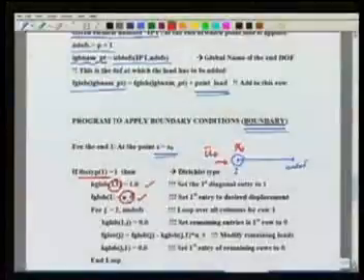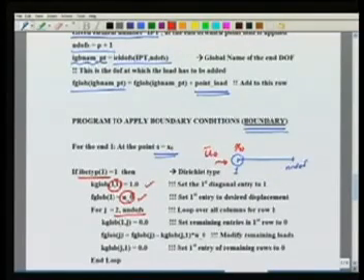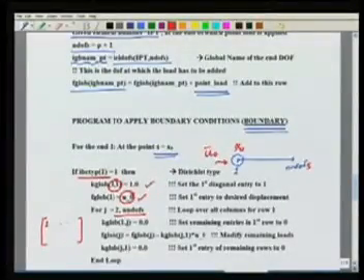Now what do I have to do? If you remember, u0 is already known, so it has to be eliminated from the rest of the equation. So what do I do? I loop over the rest of the columns in the first row, that is column 2 to column n dof. Okay. I loop over these columns and I simply set the value of these column entries to 0. So that is, I am going to set this one to 1 and everything else I am going to set to 0. Okay. So what does it give? So my first equation gives u1 is equal to u0 automatically.